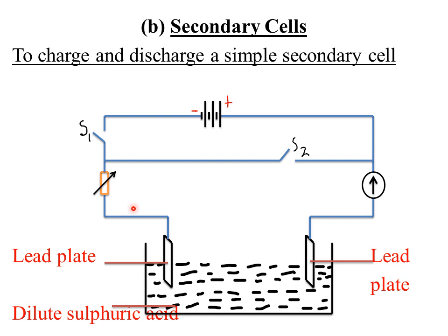That's why it is not advised to light a cigarette near a charging battery, because during that process, oxygen and hydrogen gases are produced which are highly flammable. Highly flammable means they could easily catch a flame, they could easily burn, which could be disastrous to other components near that charging accumulator.